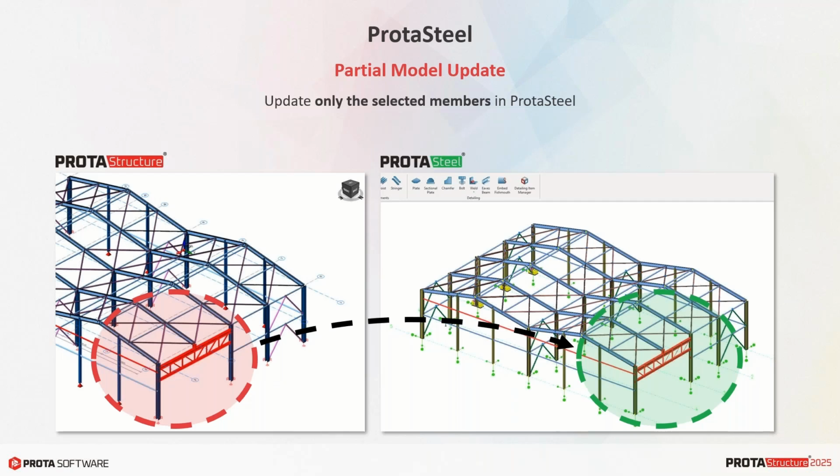ProtaStructure and ProtaSteel enjoy a seamless data communication and update system. You can update the model in ProtaStructure and reflect the changes to ProtaSteel seamlessly, even if you finished connecting and editing your model in ProtaSteel. However, as the size of the model increases, the update operation can start taking time. That's because all of the members and connections need to be checked, and connections need to be adjusted to their new location or size if an update is necessary.